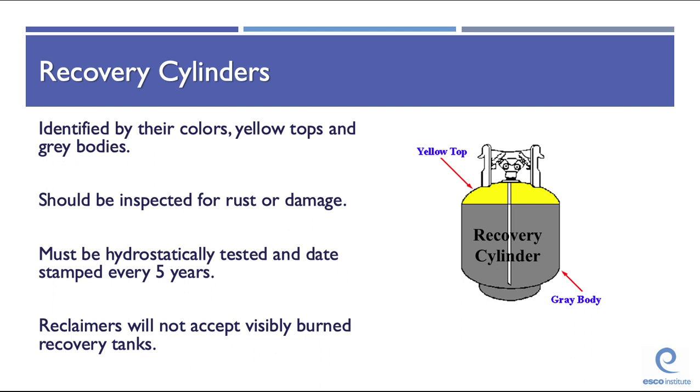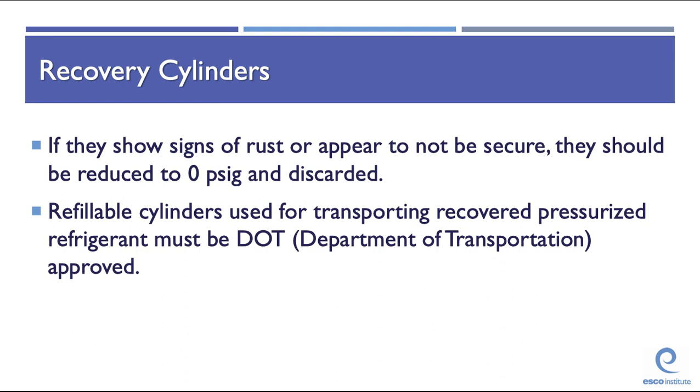Recovery cylinders are specifically designed to be refilled. Care must be taken not to overfill or heat these containers, as they can cause an explosion. Again, recovery cylinders need to be inspected occasionally. If they show rust or appear not to be secure, they should be discarded after recovering them. Refillable cylinders used for transporting recovered pressurized refrigerant must be DOT, Department of Transportation approved.